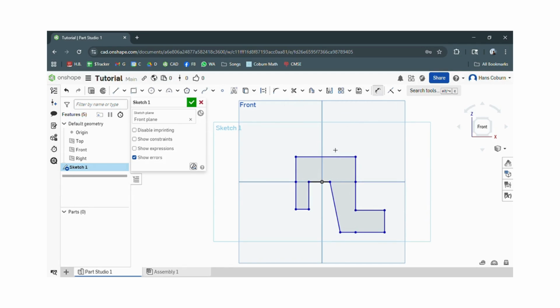Now dimensions. This is where having the pencil version is really helpful if you've already got your dimensions sorted out. For example, I know that this is supposed to be 32. Okay, already scaling my drawing down to size. I know the whole thing is supposed to be 50, but I have to take this piece by piece. So this bit here is actually just the thickness of the top, and I want that to be 5. And I need the rest of this to give a full height of 13. So 5 has already been accounted for, so 8 more millimeters there.